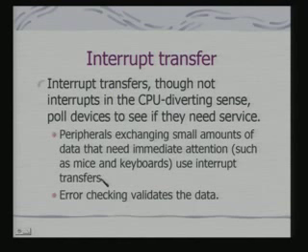You can say that this is a polled bus. The host initiates the transfer. So interrupt transfers are periodically initiated by the host to check whether these devices require immediate attention or not, and that is why they are called interrupt transfer.